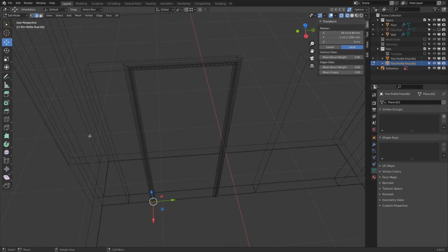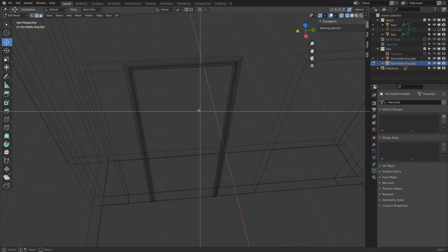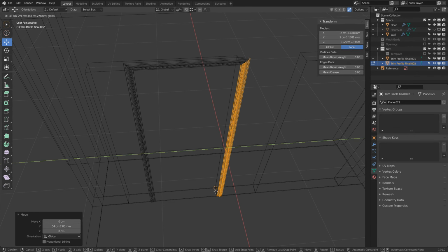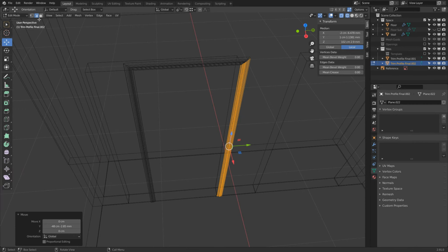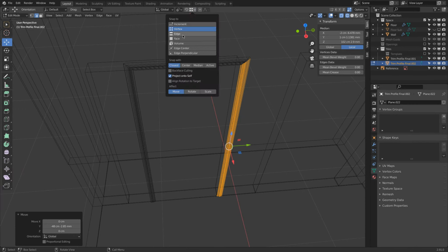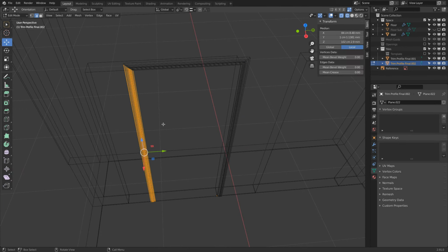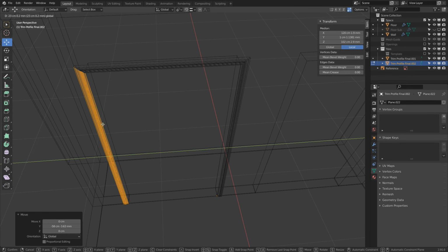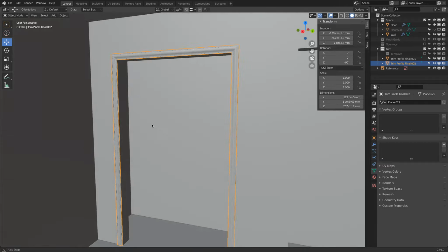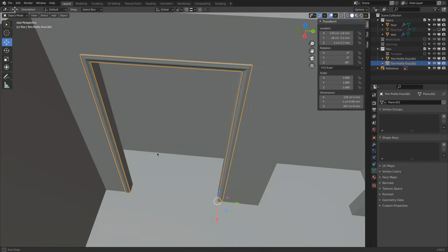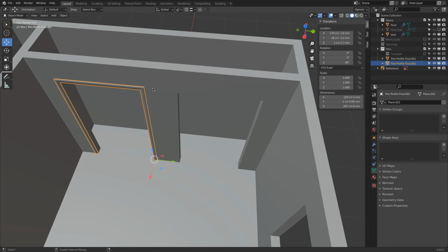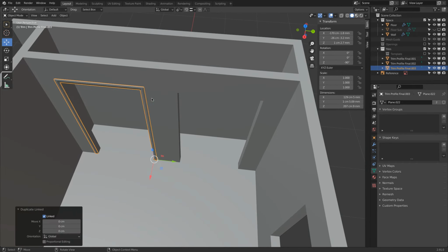edge select, Z, and go wireframe, AA, B, select only this, and just move all that stuff over and snap it back. We can actually also now go and snap to edges. AA, select this, move everything back, and then I snap to the edge of this opening. So easy. Super easy actually in Blender. This is a task in SketchUp that is really painfully complex.